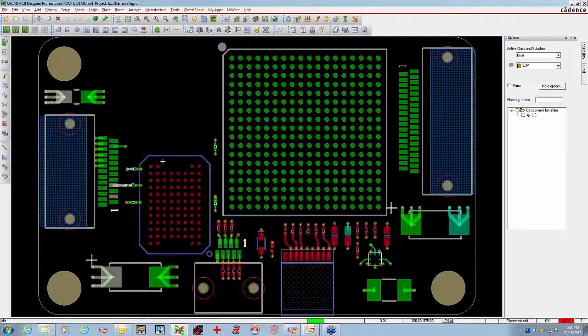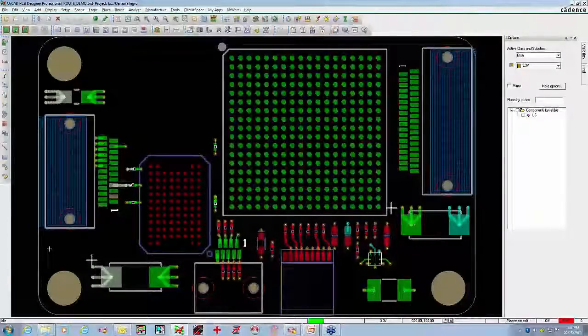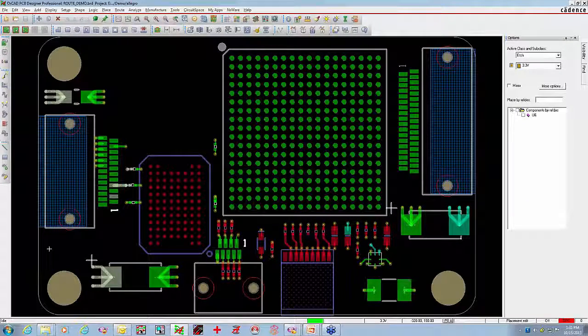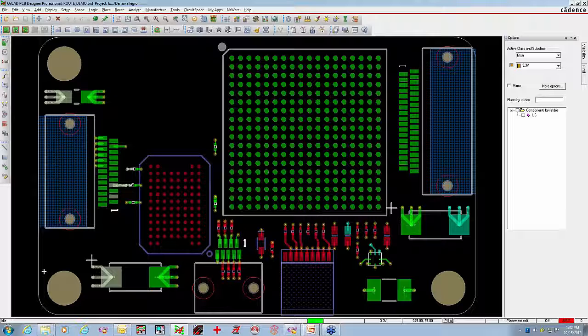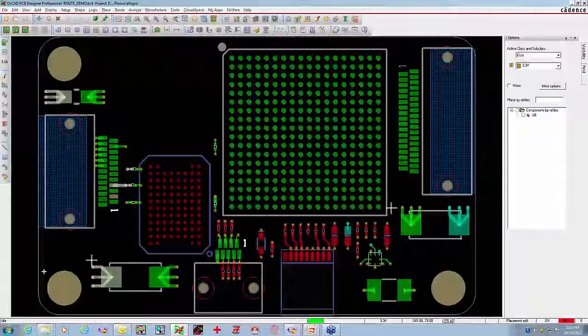The next thing I'd want to do, oh, and one other thing, in the constraint manager, we also have the ability to set a clearance from just a plain drilled hole in the design. It can be an unplated drilled hole, like you see these mounting holes. So I can set up a clearance from any trace or any via or pin, or any shape that's going to be poured around these unplated holes. I can set a DRC distance. I don't have to necessarily use a route keepout. I can simply put in a clearance, and I can set clearance to those particular objects. So I'm also showing you here that you don't necessarily have to have a route keepout. Whatever I have set for my hole to line clearance or hole to pad clearance, that's directly passed to the Autorouter from the constraint manager. So there's a number of ways you can utilize these route keepouts or specify clearances.